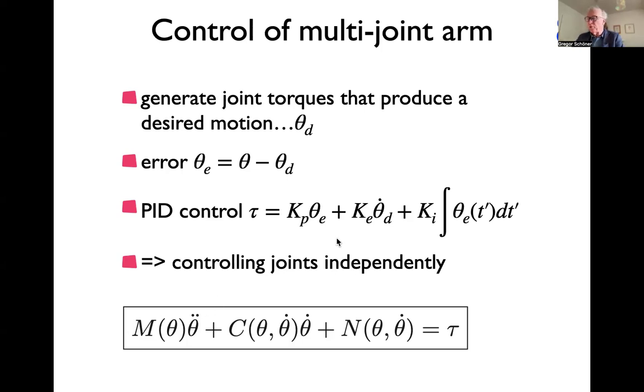And the computed torque controllers, where you compensate for these forces, are also now common. They were not common for a long time because of computation constraints. They make it a little bit milder. That is, you are not experiencing fully the interaction torques as perturbations or disturbances. You're already sending something that anticipates that these interaction torques will arise. But I'm not going to go into that in the exam.